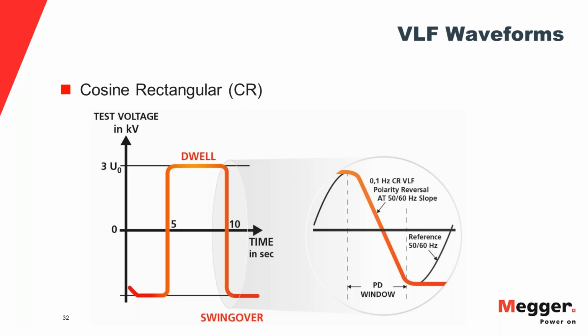So this is the wave shape, okay? So you have a DC-like plateau, a dwell time. Also, during the end of this plateau in the last second, it is possible with a still patented technology to measure the true leakage current, which you cannot measure with the sinusoidal wave. And then you have the steep polarity reversal into the other polarity. And if you blow this up, you see when you have the 50 hertz reference that the slope of this polarity reversal is similar to power frequency. So this is the original VLF as it was invented in the mid-80s.